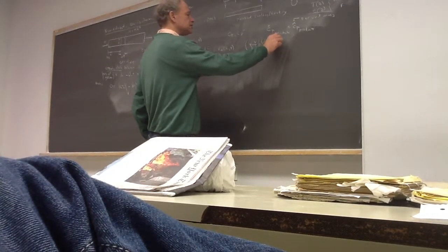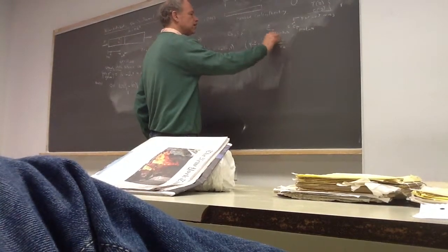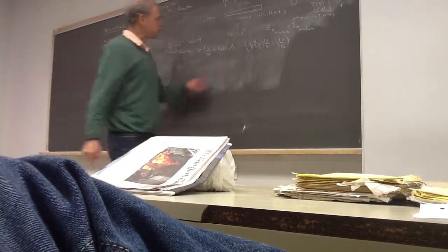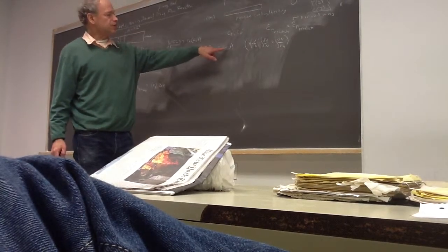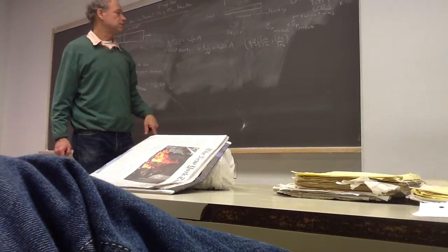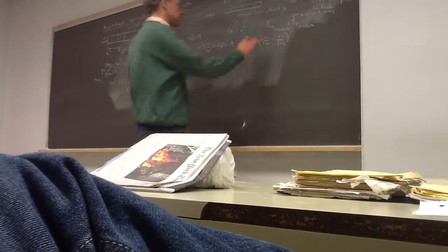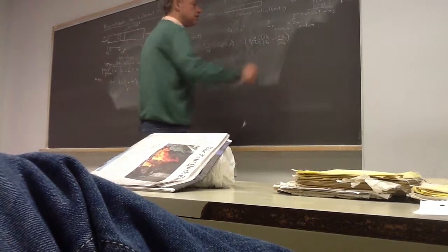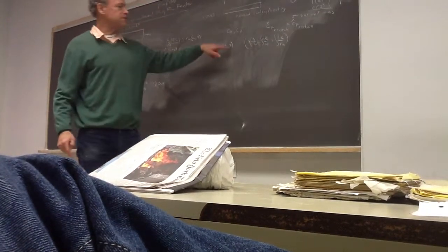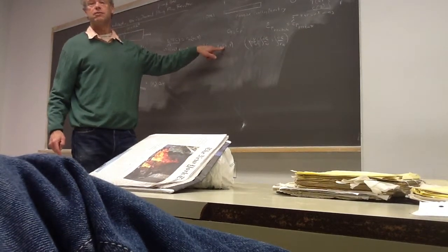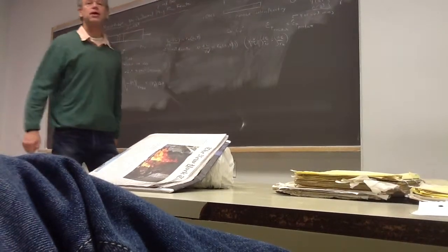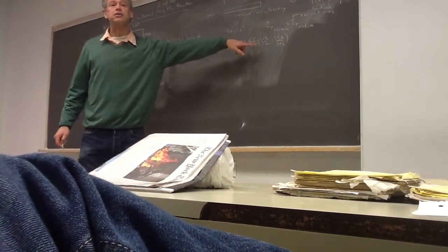And then I would just get dC over RA, which is just the design equation. Shouldn't it be dC on the right? Yeah, dC. But I can't do this here, because RA depends on T and T depends on C. So until I know T is a function of C, I can't do that. If I knew T is a function of C, I could do this.